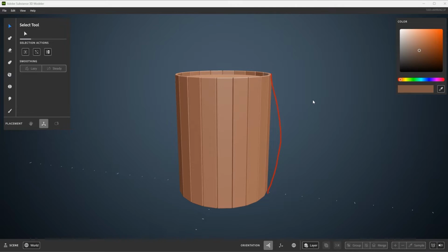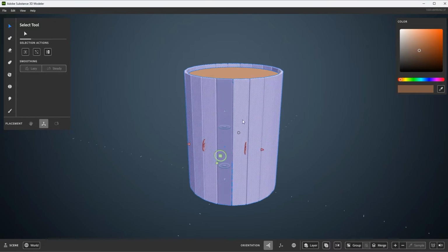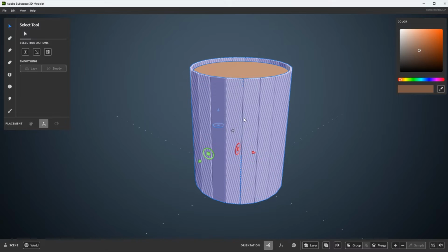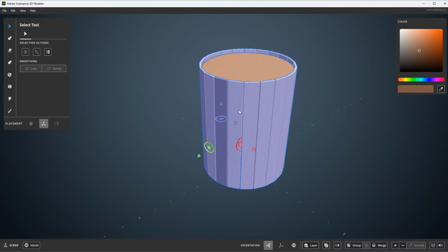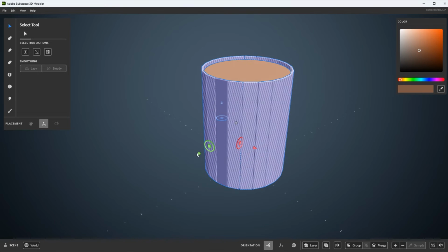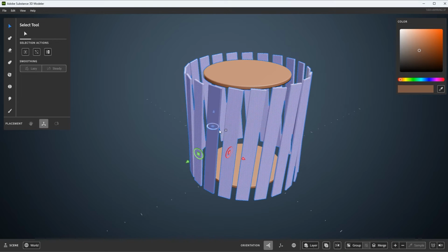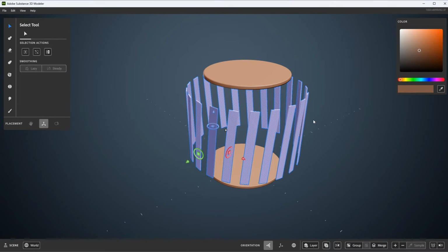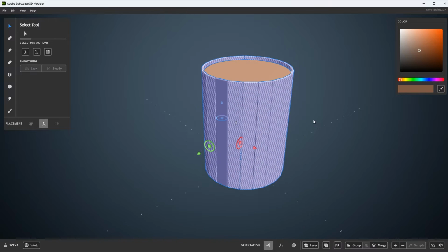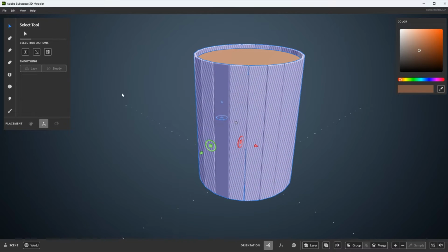All right, so what we're going to do is select our plank. Now, one of the great things about using that repetition is that all of the planks are basically instances, and they are now going to be linked. So I can do some operations just on this single plank. You can see here I'm just rotating. I can rescale it and do things, and all the other planks are going to update for me, which is pretty cool. But what we're going to do is an actual warp.